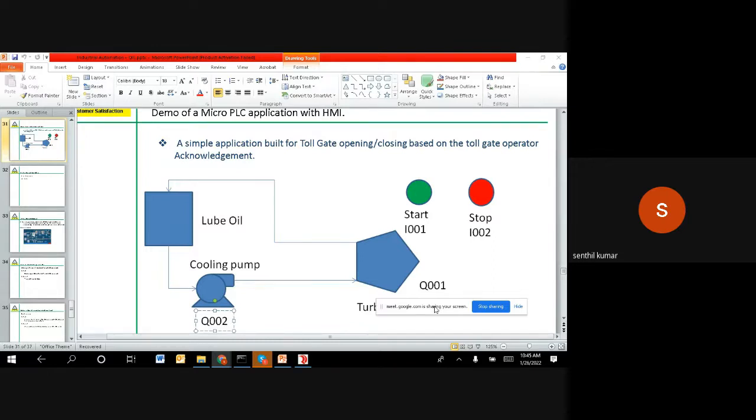As long as you know the on delay timer and off delay timer, the exact utilization and the exact purpose of that timer, then the remaining ones are all the same. Once you understand this concept, the others are easy to understand. It is not a big thing actually, right? So we are clear about the timer now. So now we can jump into the counter.